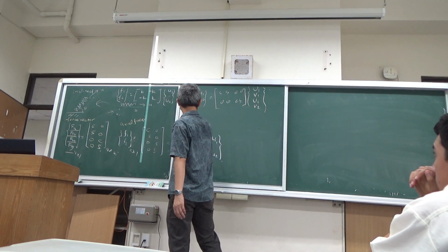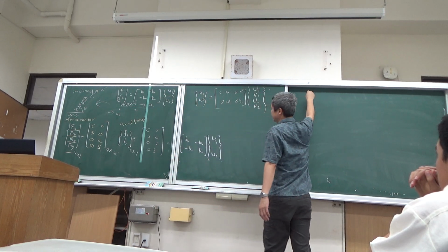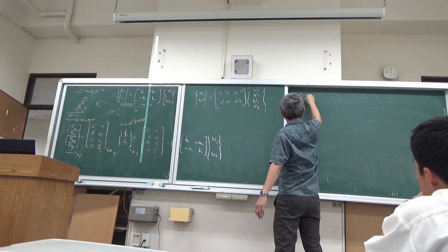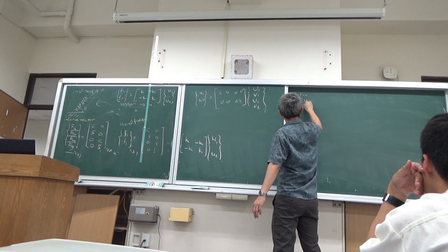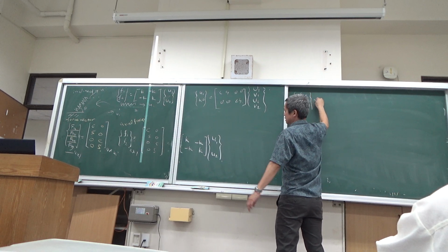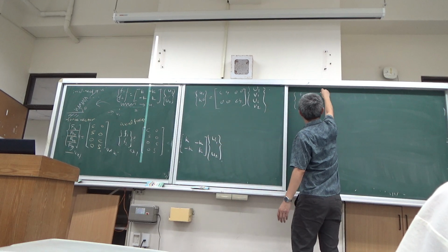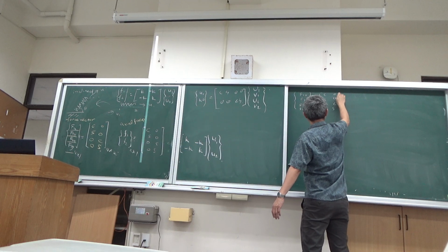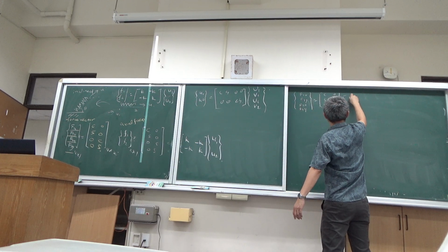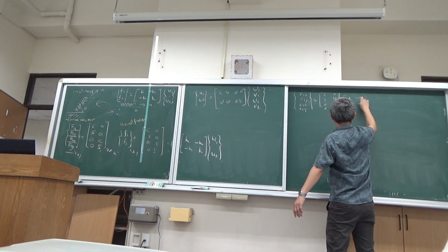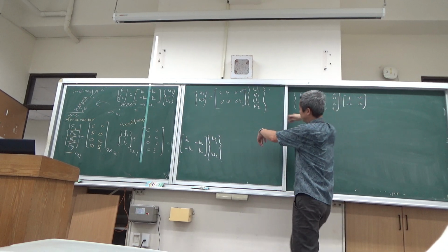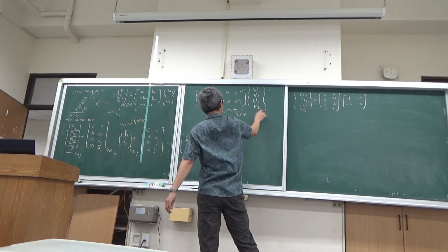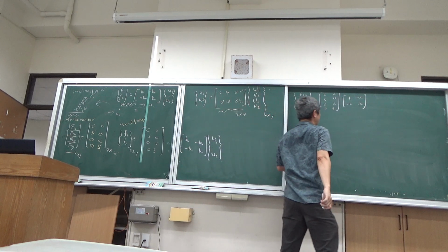so this can now be written as what? I write it over here. Your force vector F1x, F1y, F2x, F2y can be written as C, S, 0, 0, 0, 0, C, S times K, minus K, minus K, K, and U can be expressed as what? 4 by 2, 2 by 4 and 4 by 1.